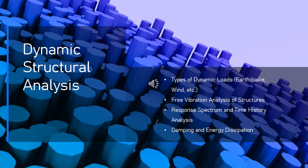9.4. Damping in structural design. In practical structural design, damping plays an essential role in controlling vibrations, protecting the structure from excessive displacements, and improving its overall performance under dynamic loads. Damping systems are often incorporated into the design to reduce vibrations and improve the serviceability of structures.